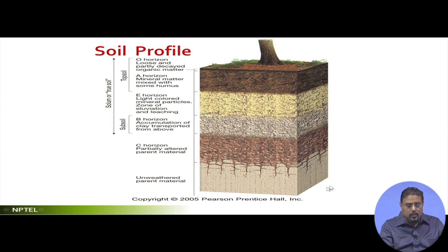Basically this is the parent material over which some soil surfaces came in, either by water erosion or wind erosion, or it got created by granulation of all these things. Over the years there had been some kind of pressure and this particular soil became more granulated. Originally there was a parent material, and along with that there may be a mix of decayed vegetation or some other organic components. So it keeps on changing, and it takes thousands and thousands of years. Mind you, if you consider about 1 meter depth, it takes 1,000 years to get this created.